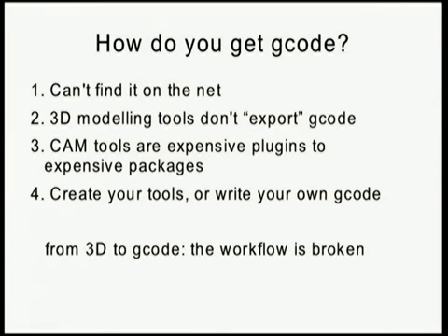However, G-code is very difficult to share. You can't really find it on the net because a G-code file will probably contain things that are specific to the machine that it was used with originally, the type of material you want to cut through, and a lot of these things make it very difficult. Also, 3D modeling tools don't export G-code for the same reasons. There are tools called CAM, which are usually very expensive additions or plugins to very expensive CAD packages, and it's not worth spending $16,000 to run a $3,000 mill. So you're faced with creating your tools or writing your own G-code.